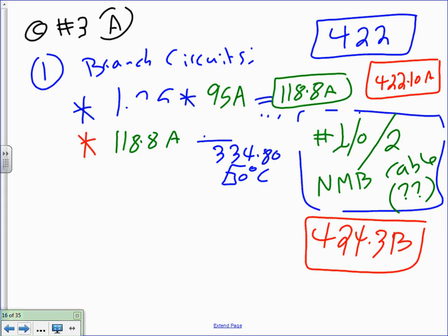Is there a reason why you raised 310.15 there? Yeah, because it's a heater, and the heater tells you 1.25. It's an appliance and it's a heater, so a bunch of things apply to it. Between the heater and the appliance, you multiply by 1.25. Cool? So we need to go down to 334.80 to size it.